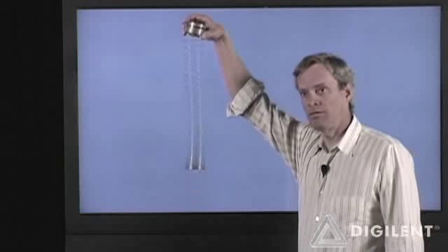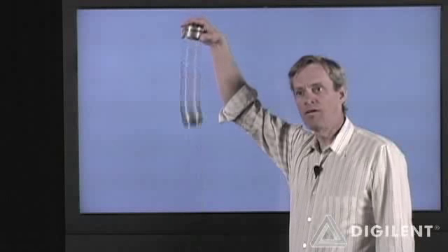Okay, here is an example of a lumped parameter system. It's a simple Slinky. Okay, if I hang the Slinky from one hand and move my hand up and down very slowly, the bottom of the Slinky moves up and down. Now, this looks like a spring with a mass at the bottom of it. At any given time, the spring is either compressing or expanding. All parts of the spring are doing the same thing at any given time. The mass, which consists of several coils of the spring at the bottom, is not really stretching.